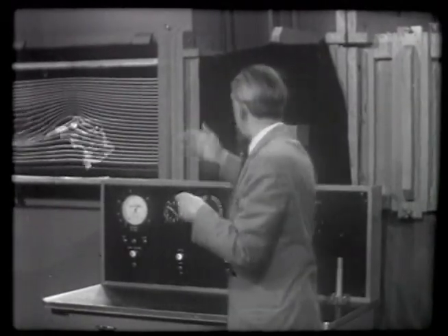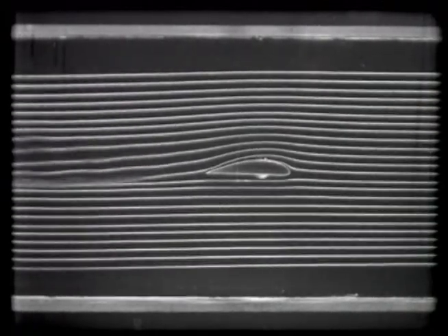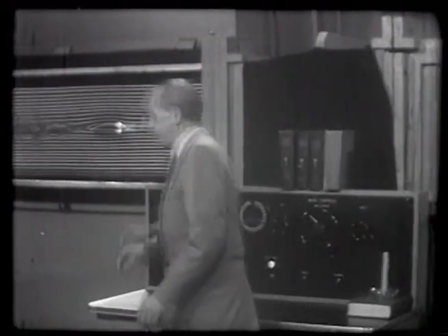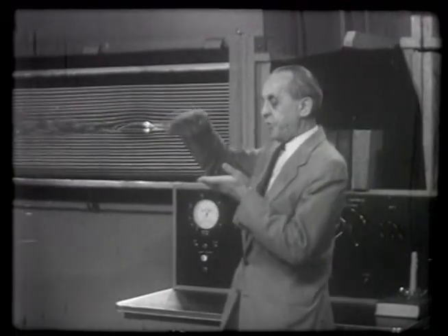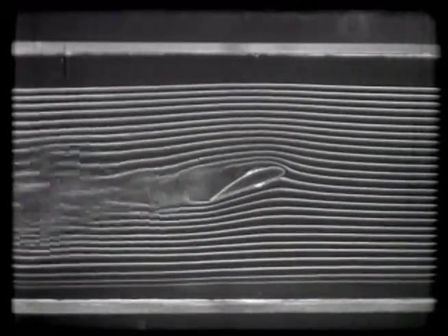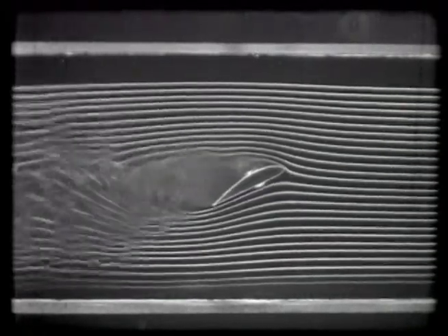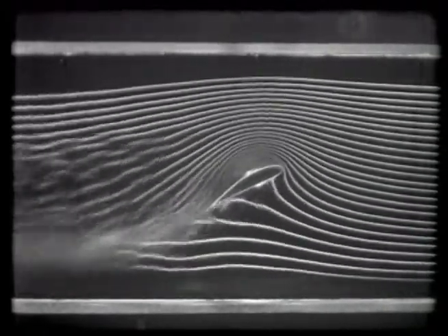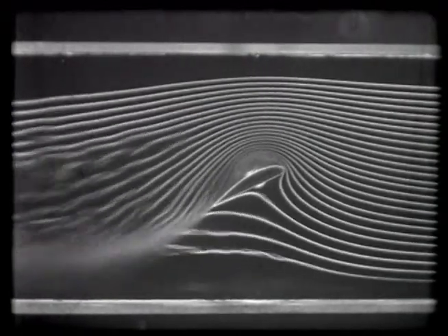And let's look at another model which has now a blowing slot on the surface. Now we have a section in the tunnel which has on the upper surface one slot where we blow out the air over the upper surface so that we can now accelerate the boundary layer and in this way get it attached, reattached. You see, I start it now, and when we now blow, you will see that it reattaches. It actually, at this point, it's really a little bit too much blowing.